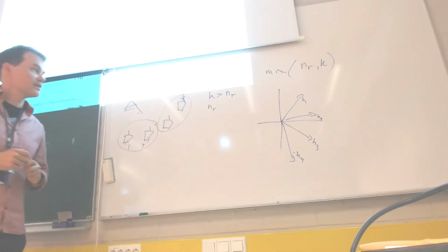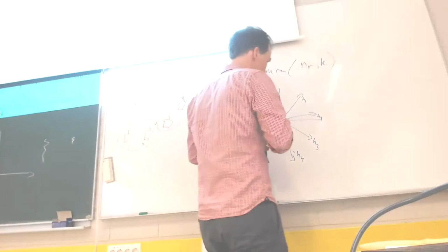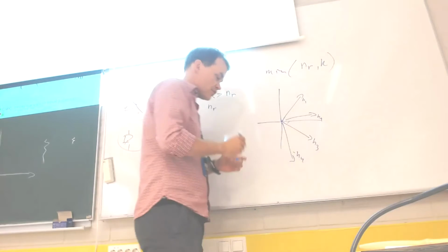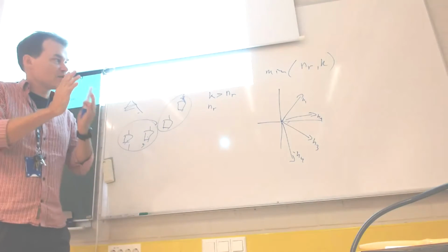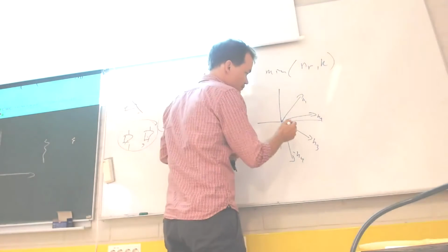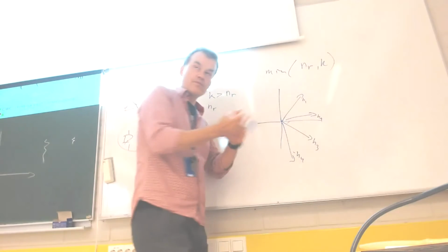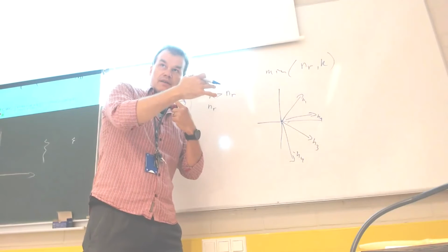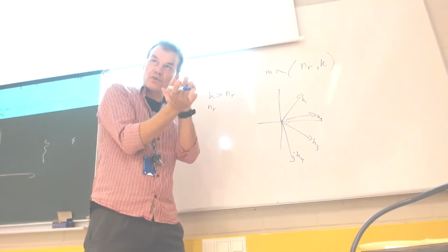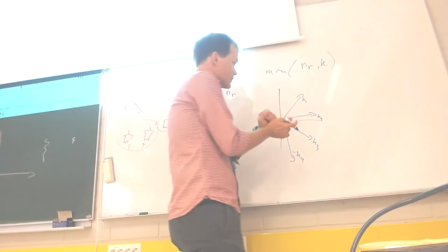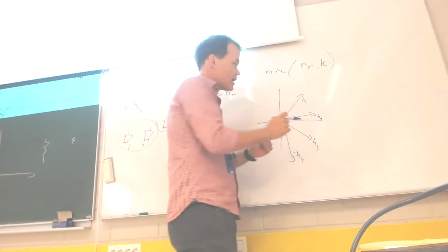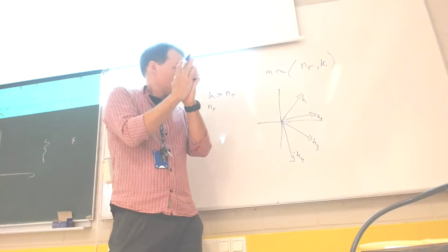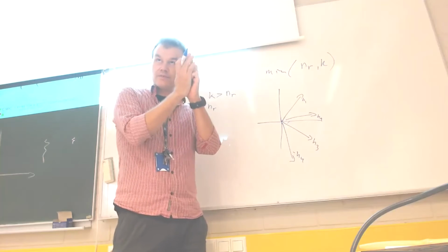Yes, they are nearly orthogonal, right? So if we choose user 1 and user 3, you can see that the matched filter projecting one user to the other user's null space does not reduce the gain, because they are already almost orthogonal. On the other hand, scheduling user 1 and user 2 is not that good a strategy because they are more linearly dependent.